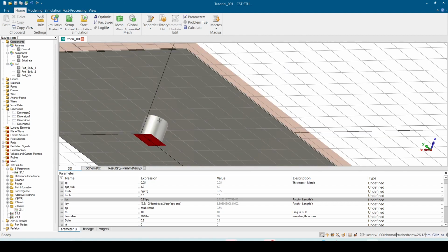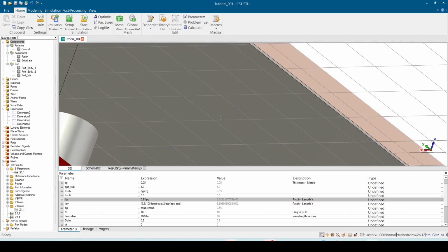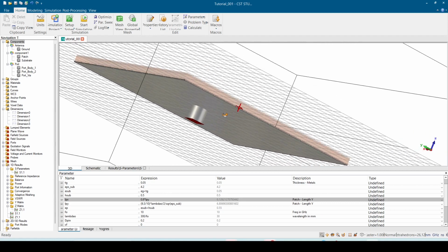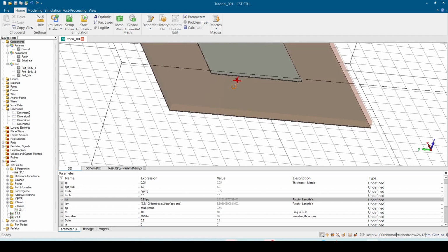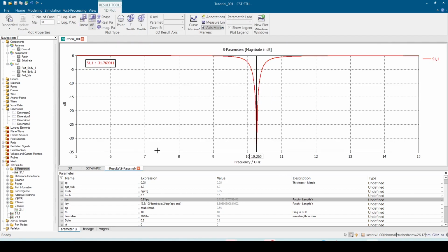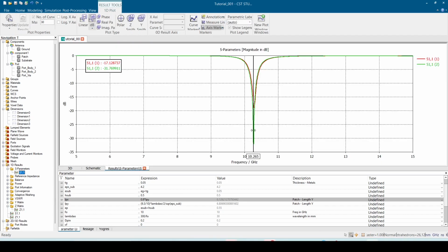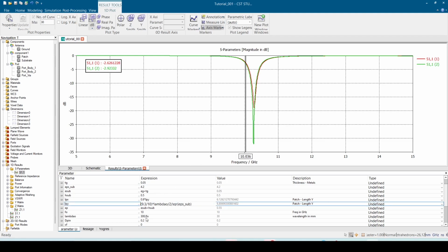And usually you don't if you do any antenna, because the feeding mechanism is the same. For example, if you have a via, you cannot use a different thing. I cannot really scale it to very big or very small. That's why it always needs a little bit of tuning. So here, the last thing, we know that the patch needs to be a bit bigger with this ratio, right? Between 10.27 over 10. So I know that I want it to be bigger, right? So I will say, I want to multiply by this.